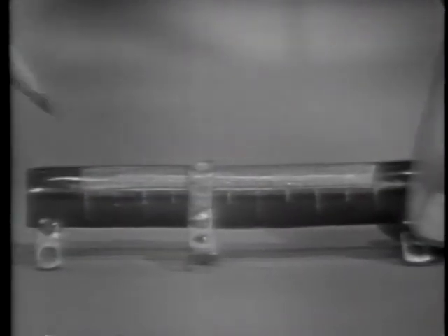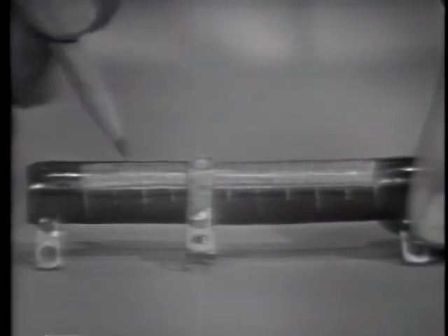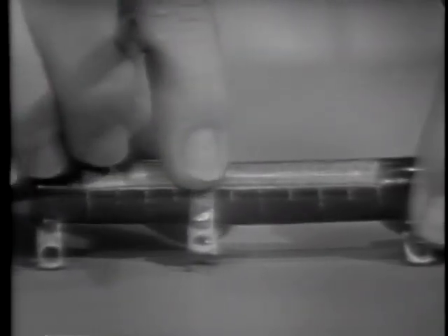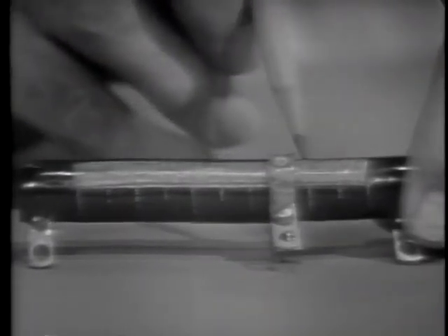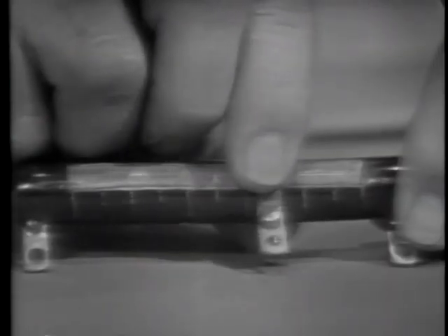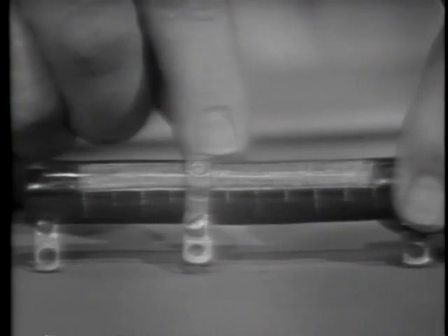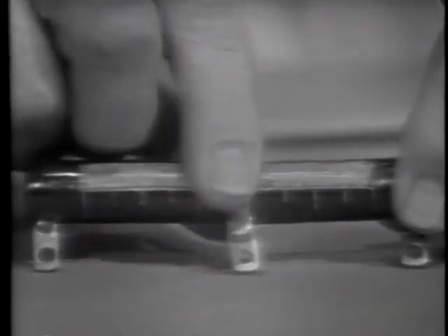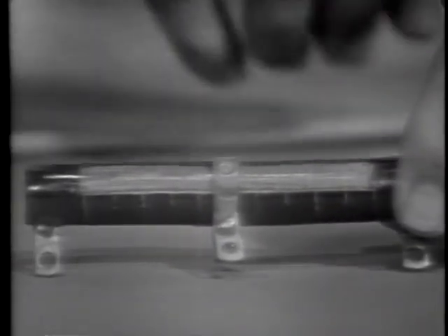This one is a wire-wound fixed resistor with a variable sleeve here. Now, it's made of wire very similar to the wire that we used in the demonstration earlier. By moving this sleeve, we can change the length of the wire, say from this contact to this one, thereby changing the amount of resistance. Let me slide the sleeve. As I slide the sleeve down, I increase the length of the wire, which means that I have changed the resistance from this terminal to this one. So by moving this, we would have a variable resistor, wire wound.